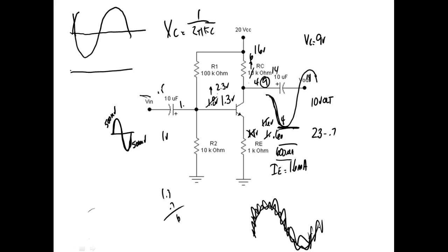So what we do to look at the bandwidth is we use a function generator, and we start off with a real low frequency until it starts passing the signal, and then we go until the signal starts dropping down. And then I can look at the bandwidth. What is bandwidth, by the way? Anybody know? It's the range of frequencies that a medium can pass. So now you know, when they start talking about more bandwidth, that's what they're talking about: the range of frequencies that you have access to. This one has a bandwidth we call F1 to F2, and it occurs at what we call the half power point.